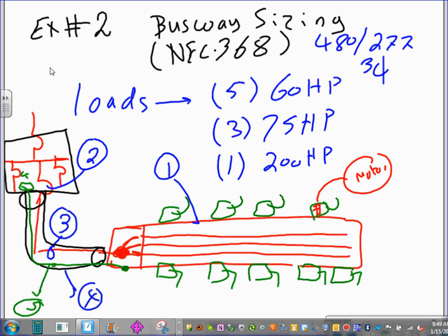That's one way. Or it can stop right here, come from here all the way up and feed all these loads. At the end of it, you'll have a big junction box. You bring a conduit to it and feed it from the main panel. That's what we typically do with busways. Plug-in busways, guys, don't go all the way to the panels. If you look right here, here are all the plug-in busways. Can you guys see them? All these machines are plugged into them. They typically go where the machines are located, and then you feed them either through another busway called a feeder busway, like in this project, or through a conduit to the line.